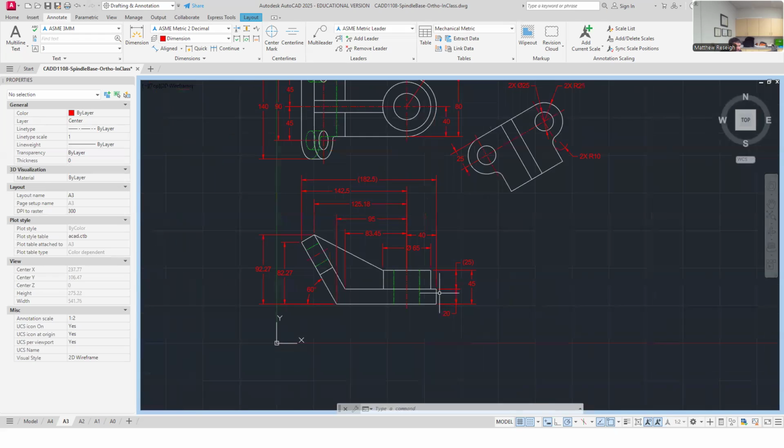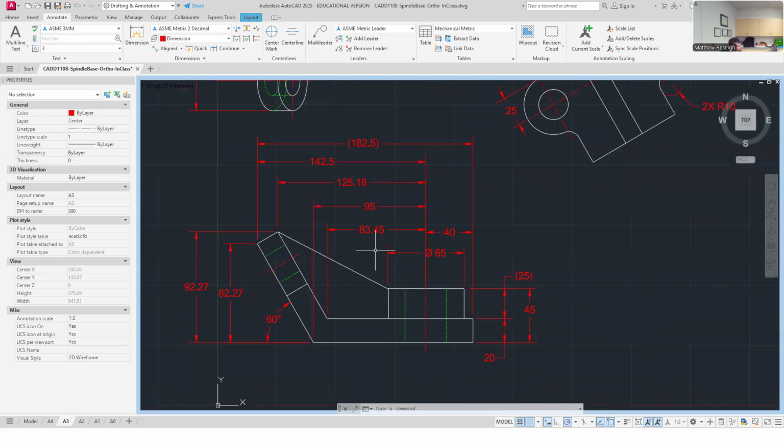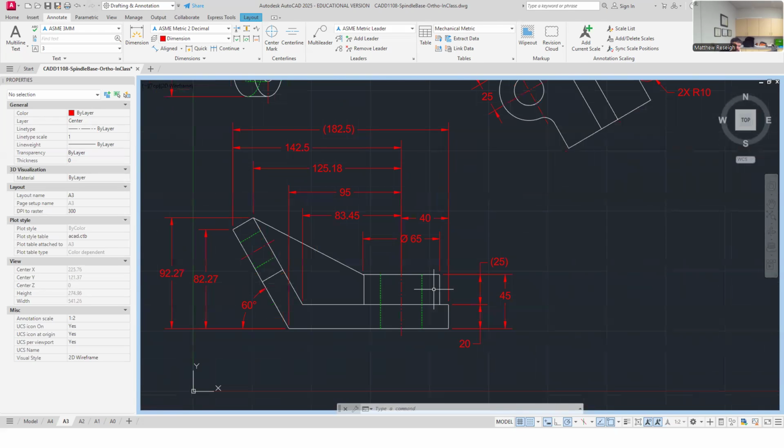Anyway, okay. That was another thing that I kind of pointed out on some people's drawings. Don't be afraid to compact your dimensions by chaining. I'm going to chain these two together probably for sure. Okay. So that's definitely sized, right? I think it's that diameter and it's potentially either 40, it's this or this. If 25 was more critical, I'd drop the parentheses and put them around this.